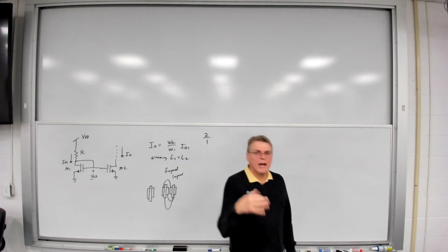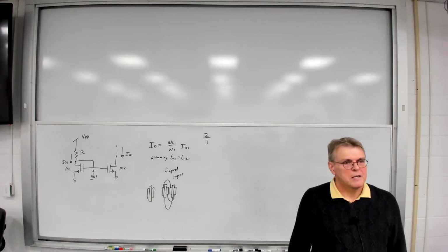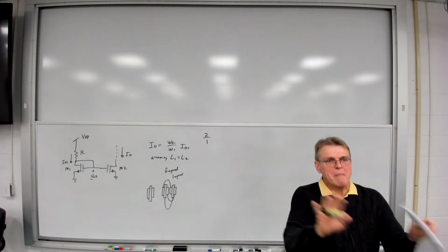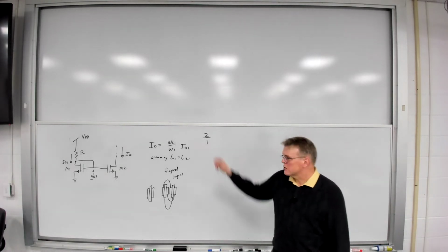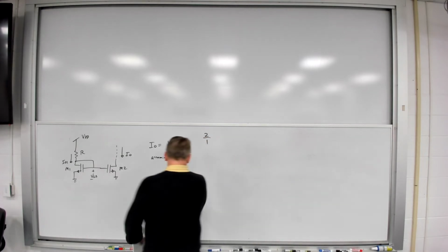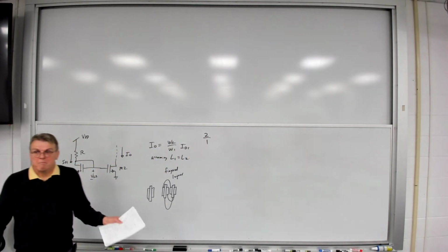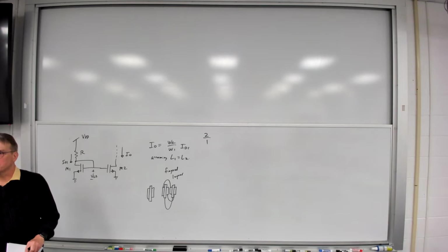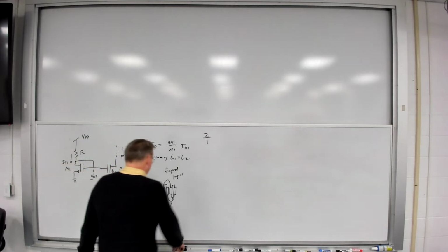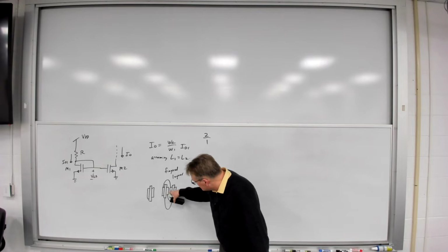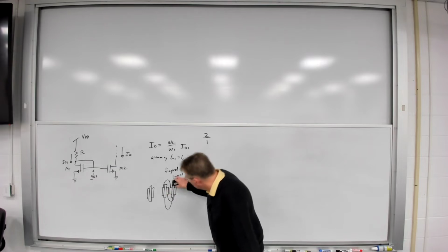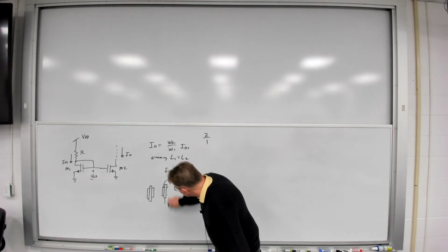So this is typically how you will do these types of ratios, by creating identical matched devices and then connecting different transistors in parallel to get the different ratios you want. And so by being clever about this, you can create basically any ratio you want between two transistors. And in fact, quite often what people will do is, you notice these two diffusions here? They'll just move those together like this.